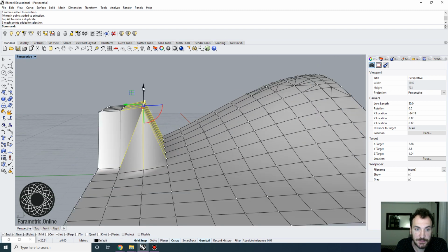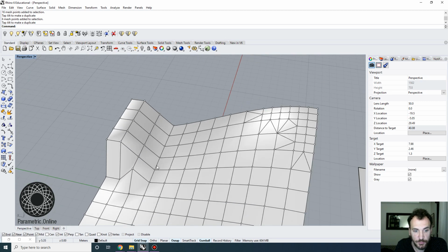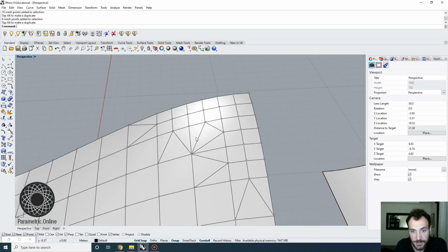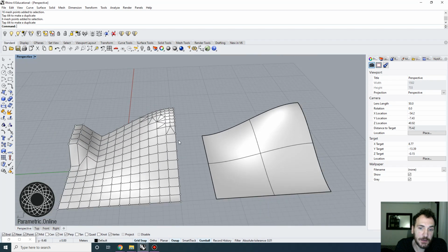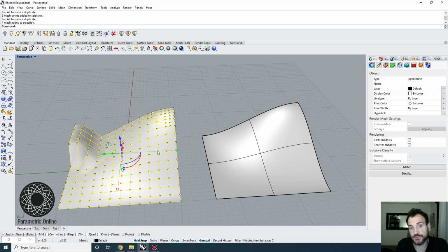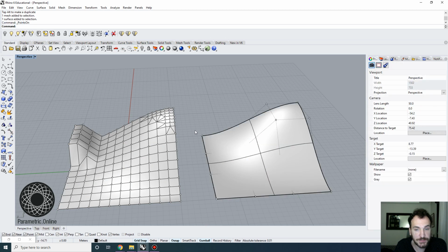And these vertices are used to construct either quads made out of 4 control points, or triangles that are made out of 3 control points or control vertices. So the difference is that this gives us a reduced data structure that is formed out of indices of points and the faces that are defined by those points, whereas the NURB surface is defined by control points that are interpolated. So that's kind of the difference between a mesh and a NURBS in a nutshell.